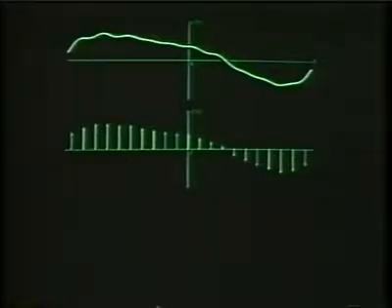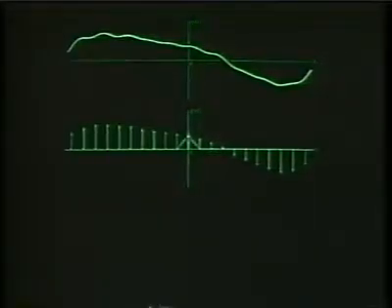Now let's do the same thing with a first-order hold. So in this case, we want to interpolate using a triangular impulse response rather than the sine x over x or rectangular impulse responses that we showed previously. So first, let's say with the sample at t equals 0, we would replace that with a triangular interpolating function. And more generally, each impulse or sample is replaced with a triangular interpolating function of a height equal to the sample height. And these are superimposed to generate the linear interpolation.